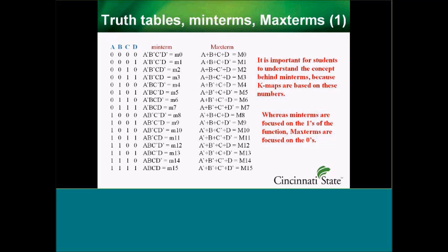Maxterms, on the other hand, is more of a side topic. I'll put it this way: most courses do include it, at least it's talked about peripherally. Whether or not you actually run exercises and do things with it, maybe not. Maxterms are mostly helpful if you've only got a small number of zeros and a whole bunch of 1s. Then you can frame the solution in that form, and they're focused on the zeros.